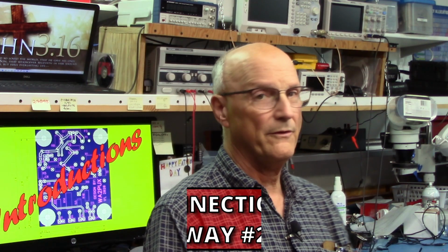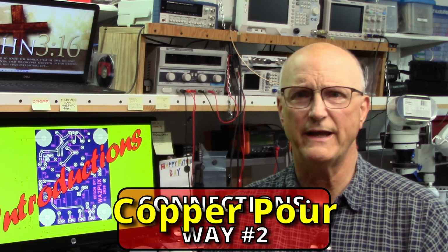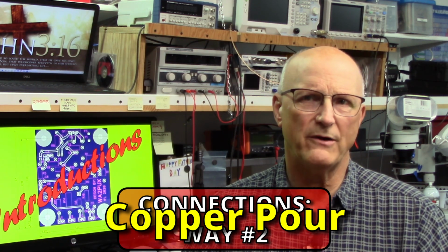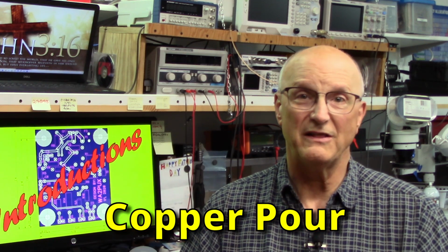But I did say that there are two ways to connect things together, and so far I've only told you one. So what is this second way? Well, the second way we connect things together is using what is called a copper pour. Copper pours are generally used only for things like the board's ground and or power plane, and are generally the last thing placed in the board.